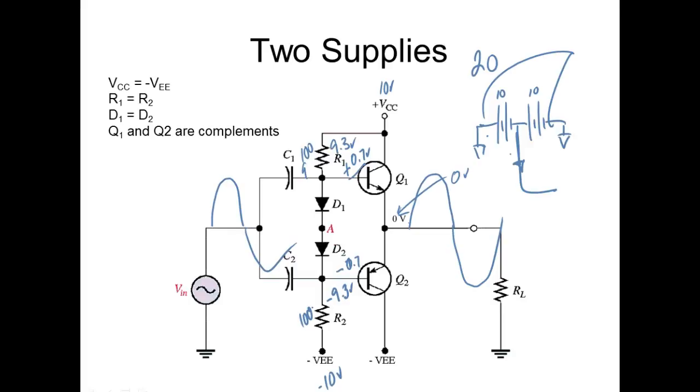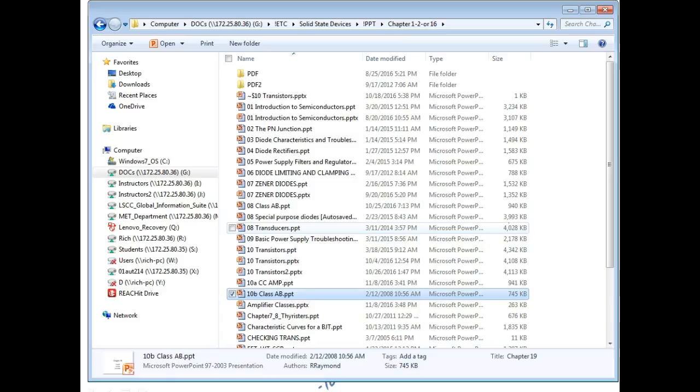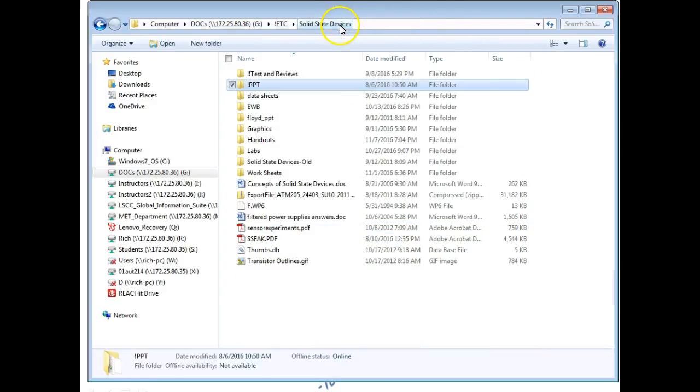And these guys here are pretty easy. But what we're going to see, so if I come over here and look at a power amp, what I'm looking for is 2 diodes in there, hooked up back to back. And why do they put them in there? Well, those diodes are there to put that 0.7 of a volt on there, right? To put the base at exactly 0.7 or real close to it, so the input signal is not turning the transistor. If I don't have an input signal, both those transistors are what? They're off.